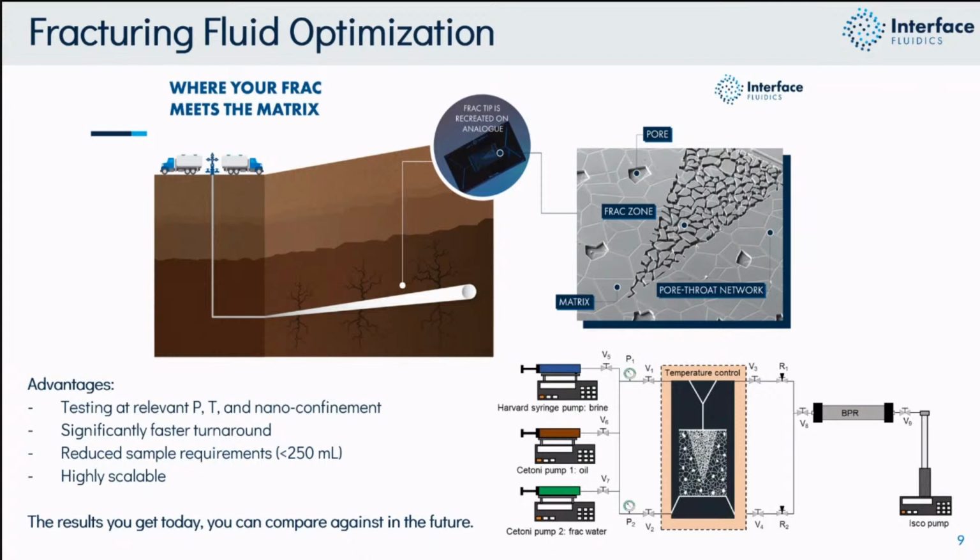So in the picture, from top to bottom. And during that process, we measure or track the oil saturation, and we can also quantify the displacement efficiency. It means how much of the system has been cleared by the frac fluid, which can show how much porous space is going to be impacted by frac fluid.